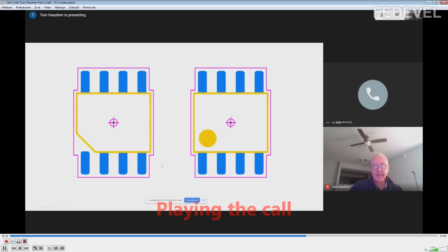I'm going to go to the next slide, and we're going to talk about assembly polarity. For assembly polarity, you could either use a chamfered polygon to indicate where pin 1 is, or a rectangular polygon with a dot. And they're both the same. I mean, they're not different. I think maybe the one on the left is easier to print and it's less data that you have to store. Could you imagine having thousands and thousands of parts in your libraries with big dots in every single part for your assembly? Your library is probably going to be bigger in size, for your hard drive or your solid state drive or whatever. The more features you put in, the bigger it gets. So having a chamfered line, we're just trying to lighten the library load a little bit, okay?